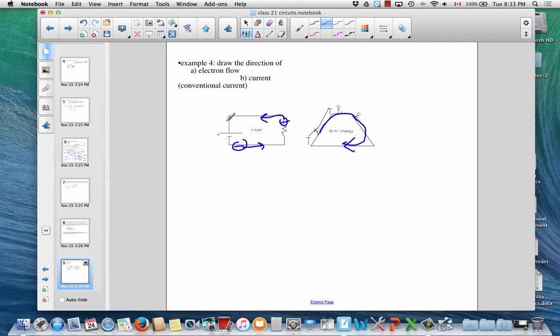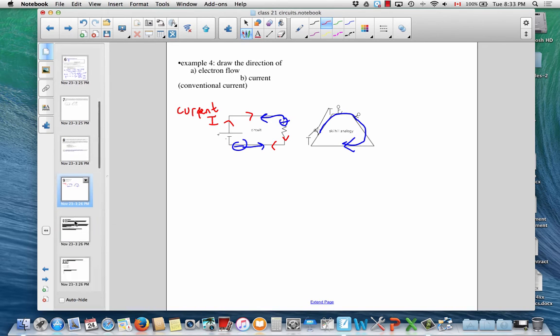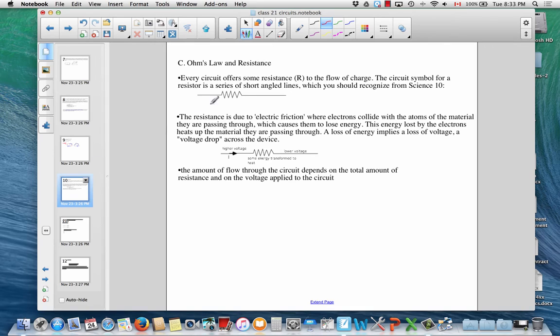But what we're going to call current, I, flows from positive downhill to negative, into the negative terminal. So current is opposite to the direction of the electron flow. Now, that sounds confusing, but in practice it's not a problem, because what we're going to call current is just the flow of positive things, and very quickly we won't talk about electrons flowing anymore.